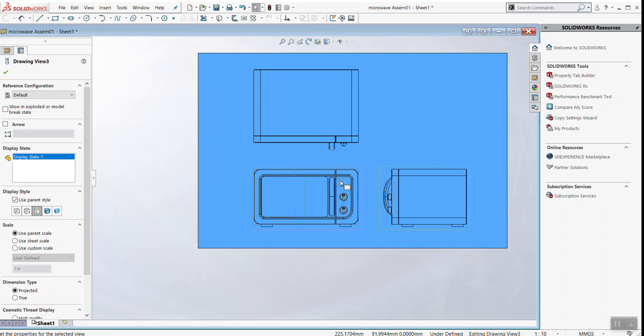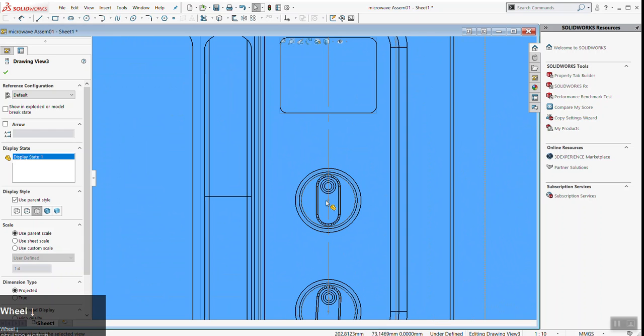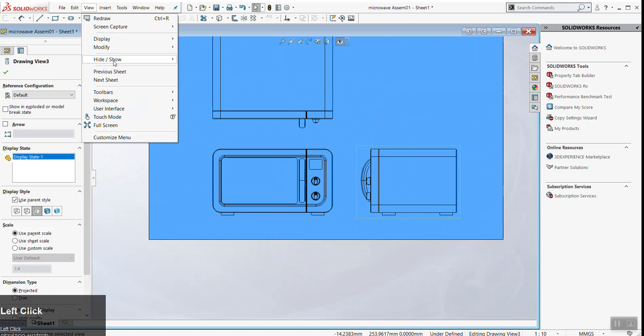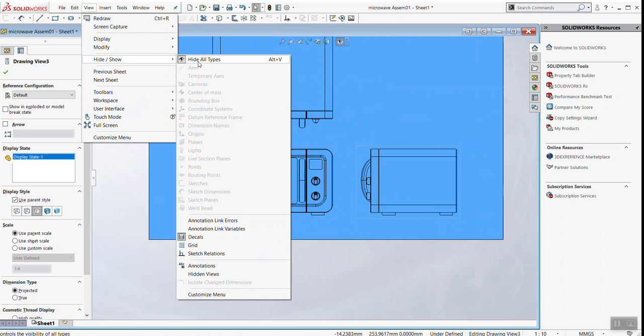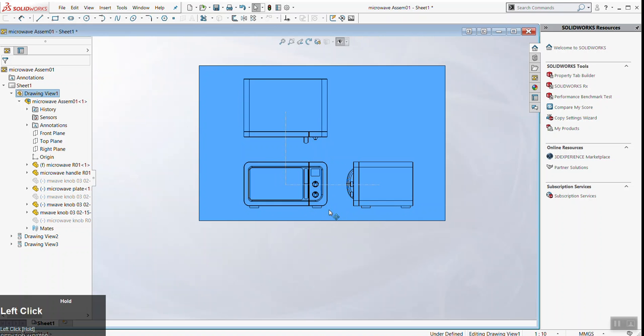I'm going to assume also, and this happened on the water bottle, it wasn't a big deal. And actually for grading, it made some things somewhat easier. For this project though, I want to turn off all these sketches. You'll notice, at least on mine, if I zoom in here, you'll see all these dots. If you just hit Alt-V with my hotkeys, that'll turn sketches off, or you could go to View, Hide Show, and just turn off all those buttons with one switch. So everyone should have something that looks roughly like this.